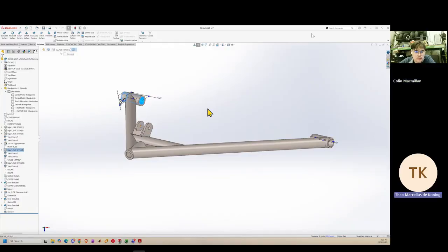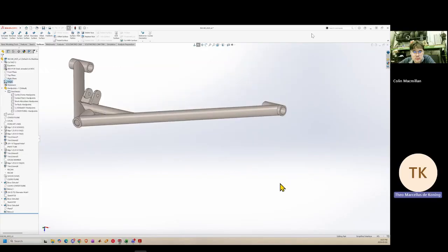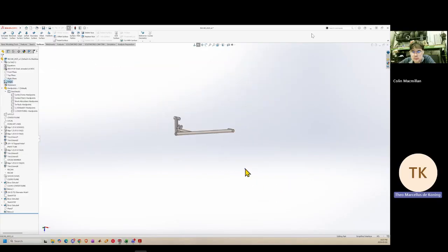Okay. But then when you drop it into your assembly, you go, okay, now where do I mate it to? Because you could pick your origin to be the center of the space here, or the center line, the halfway point of this tube. There are some discrepancies, but if your origin is the origin of the assembly of the full vehicle, then there's only one position for this control arm to go in. Okay. Yeah. Got it.